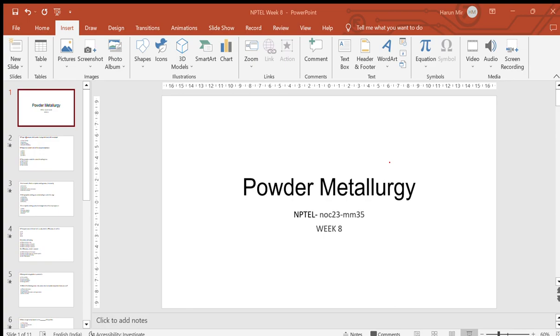At this critical loading, the viscosity of your mixture will be highest and the density will be at its peak. So this is the maximum loading of your solids that you can do in a mixture, with the highest viscosity and highest density. This is how it is defined in this equation.